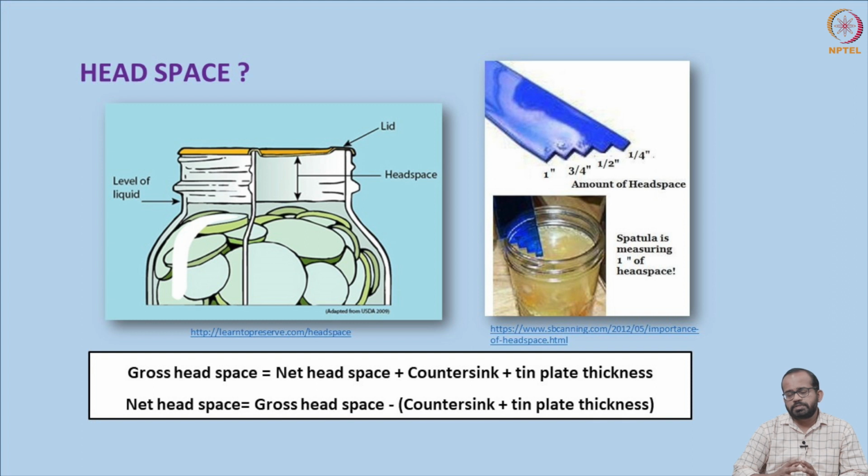This internal pressure increases the significance of the headspace, because if headspace is not present, this pressure is balanced by bulging of the cans. This internal pressure needs to be balanced by bulging of the cans, but for cans to properly bulge, there needs to be proper headspace.